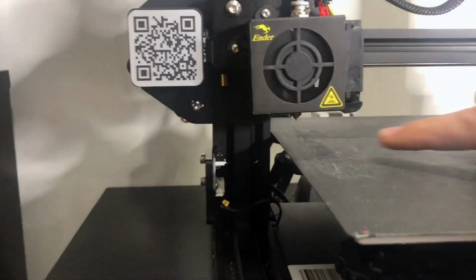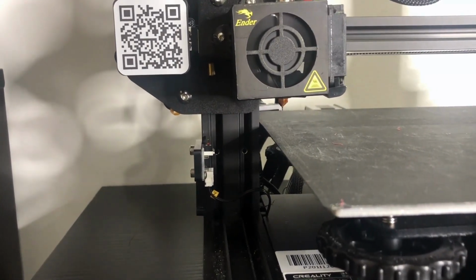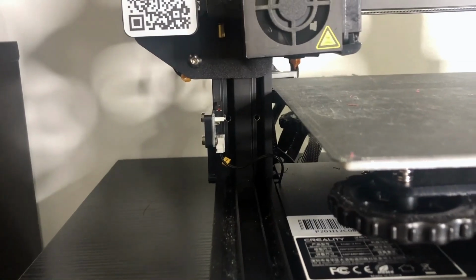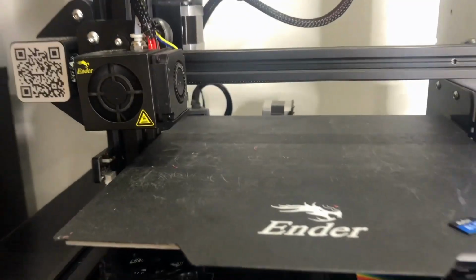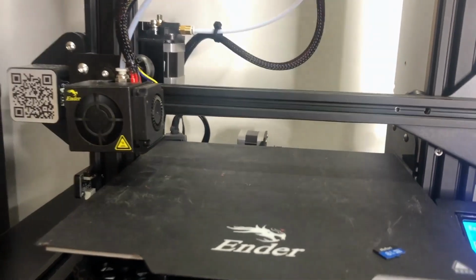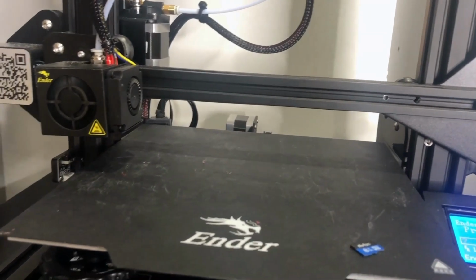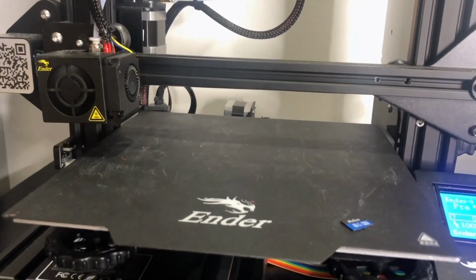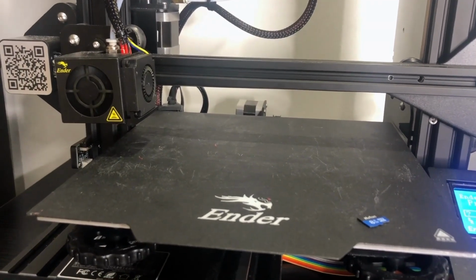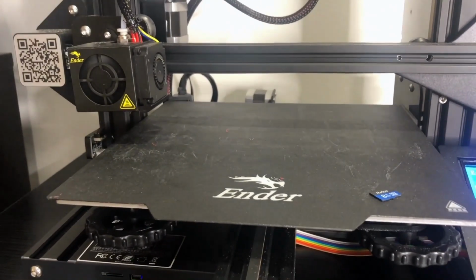This under here is our extruder head, so that is where the filament will actually come out of, and as you can see, it really necks down towards the end there. Actually, the cross-sectional diameter of that is 0.4 millimeters. It's pretty standard across printing PLA, and other materials will require different extruder head diameters, or some filament can come in larger sizes. This begins as 1.75 millimeter filament. Then when it's heated up, it extrudes at a 0.4 millimeter diameter under our bed.